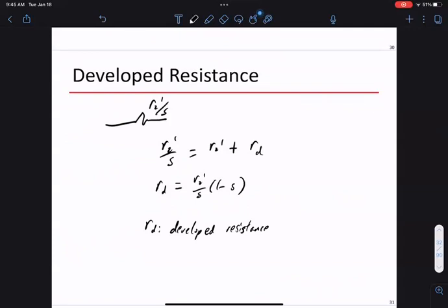Okay, the generator, by spinning faster than the synchronous frequency, is adding a negative resistor to the circuit. Okay, it's appearing as a source, but it's not appearing as a voltage or current source, right, which is different than standard circuit. It's appearing as a negative resistor at outside source. Normally you think of a generator as a voltage source or current source or voltage control current, all the kind of things. Here it's natural to think of the generator as an added resistance, a negative resistance, but added resistance. Okay, so that's where the generator comes in.